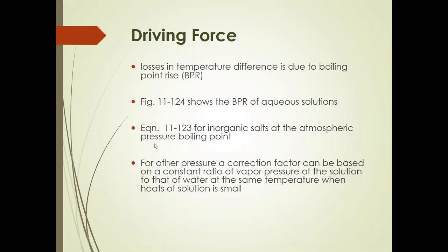Now, if the solution is not aqueous, if it's a solution of inorganic salts, in your handbook, you can also use equation 11-123 in determining the boiling point of such solutions wherein you have the presence of inorganic salts. However, you are to take note that that particular boiling point is at atmospheric pressure. So meaning at elevated pressures, this equation will not work anymore. It's only good for the condition at atmospheric pressure.